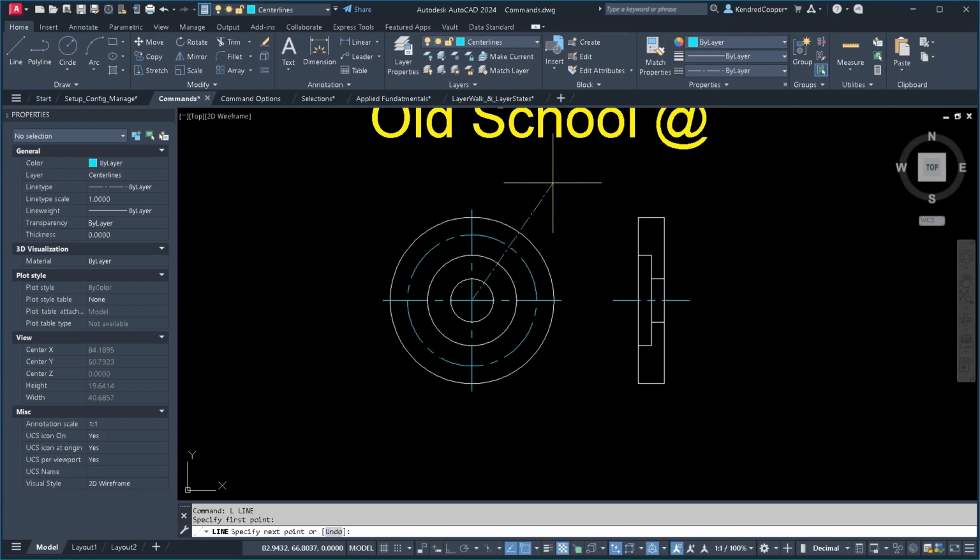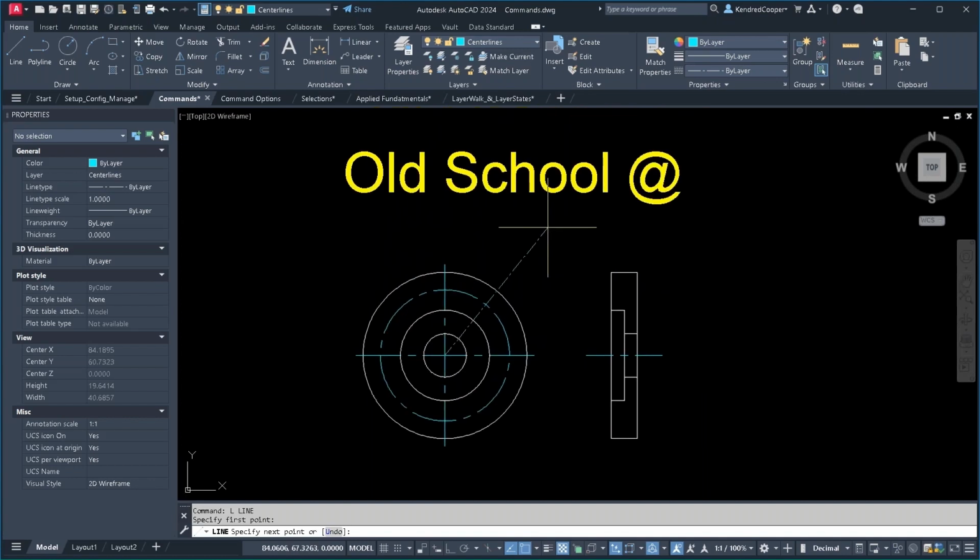There's a very old school way of entering that information. First, you're going to start out by saying at, so use the at symbol, and that basically says at my last point. That's going to be the center point. That was the last point I picked. Go whatever units, mine is going to be 10.